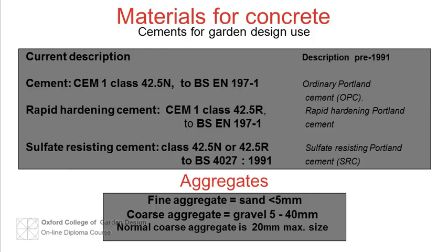There are 3 ways of mixing concrete: by hand, in a batch mixing machine on site, or ready mixed, obtained from a specialist off-site plant and delivered by mixer lorry. The choice of method will depend largely on the quantity required and any limitations on access to the site.